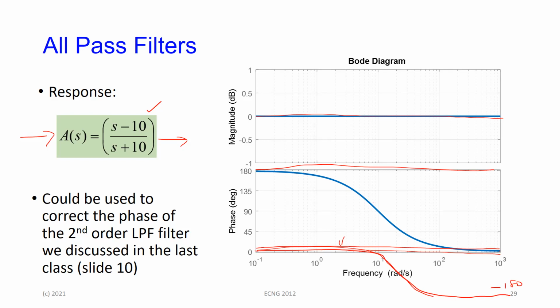We looked at the bandpass, and our particular approach was to create the bandpass response by cascading a low-pass and a high-pass filter. One created a low cutoff, one created a high frequency cutoff. And then the last one is that we created a band reject or a notch filter by running 2 filters in parallel, a low pass filter and a high pass filter, and then we added the responses at the end.